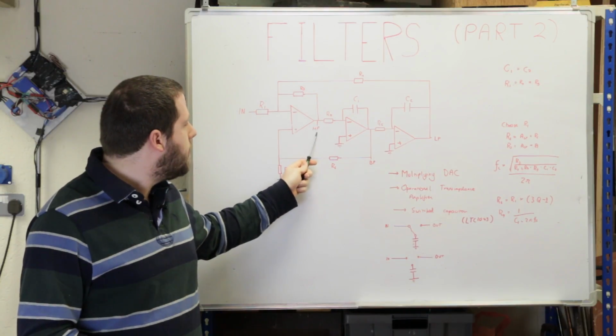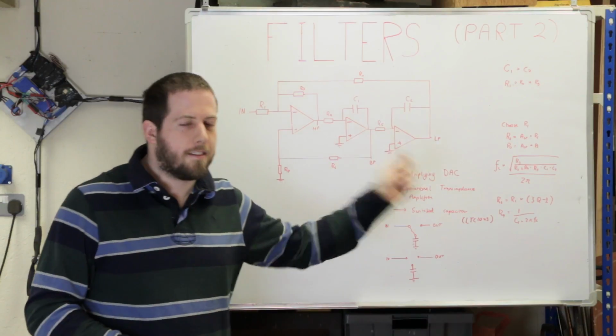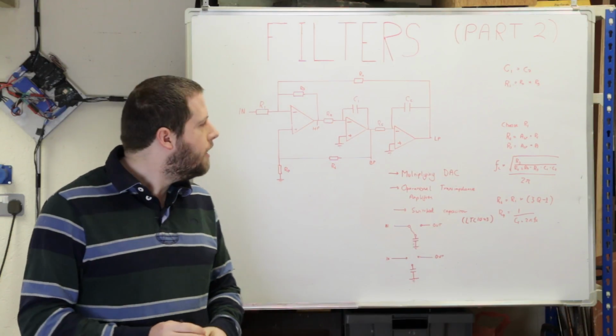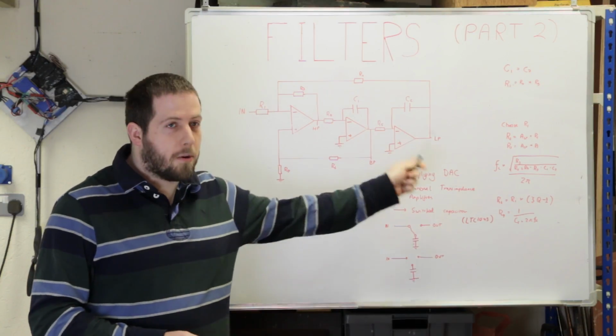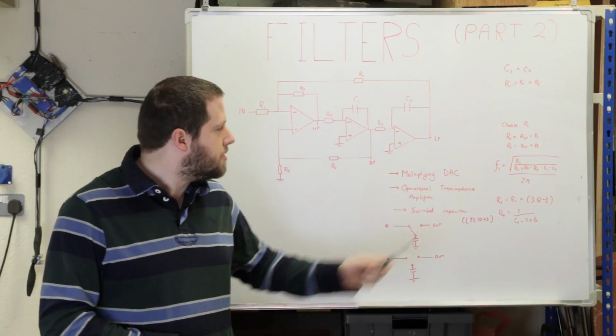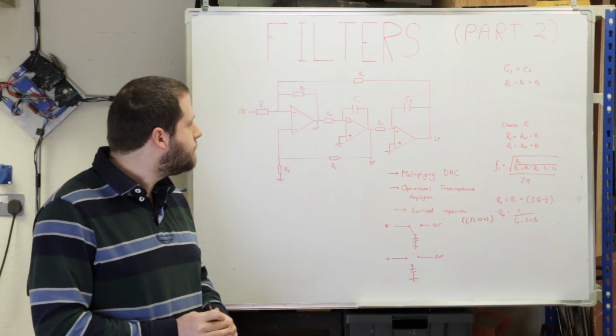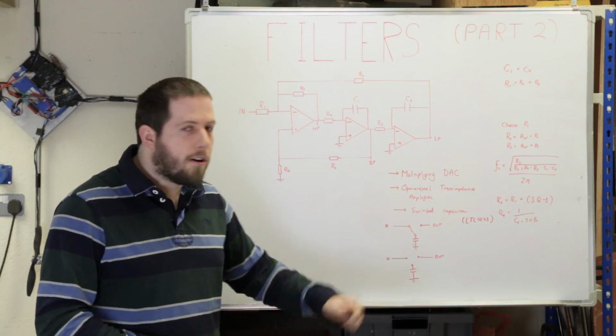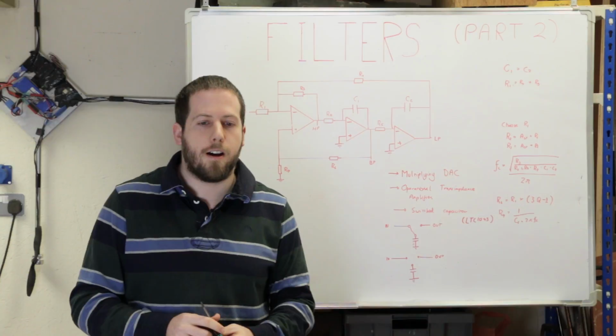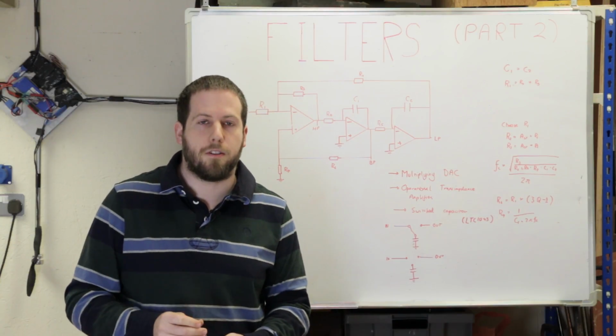When you start putting the high pass output on, you're still going to get some kind of noise coming through the filter. So you might want to put a little notch filter in the output just to try and remove that, take that noise out, using methods like that. So that's just a few more options, different ways you can do variable frequency filters.